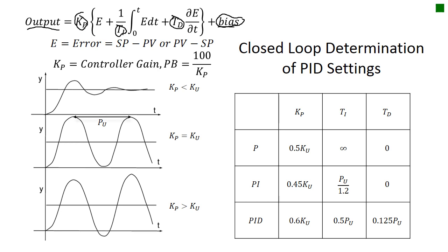At this point, we're going to slowly increase our gain until we start seeing the controller take some action. With the gain being 0, the controller only has one output, and that's the bias. But as we take larger and larger values of our gain, we can then see the output changing.